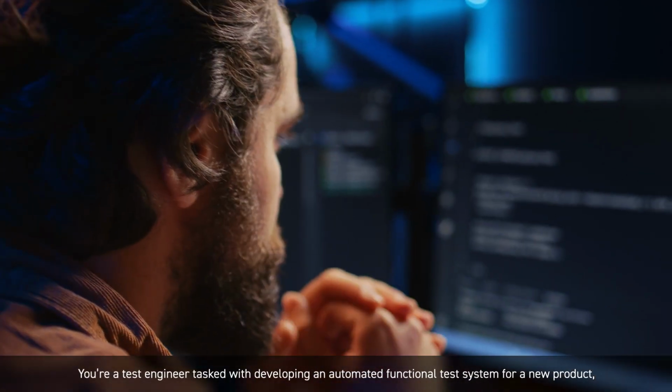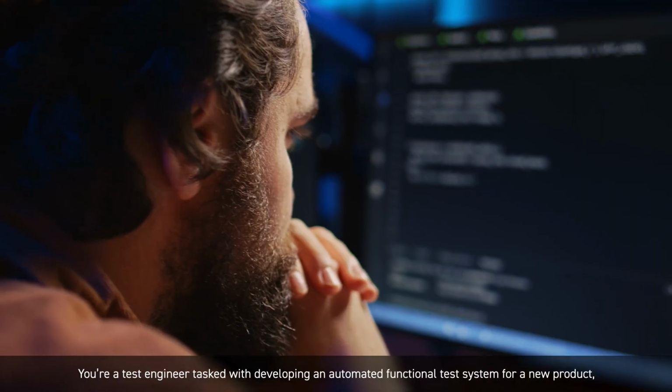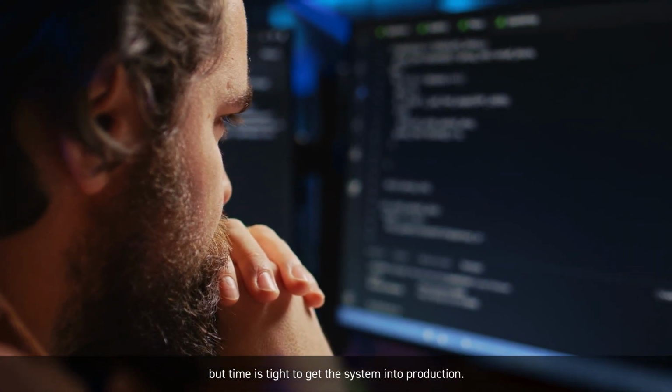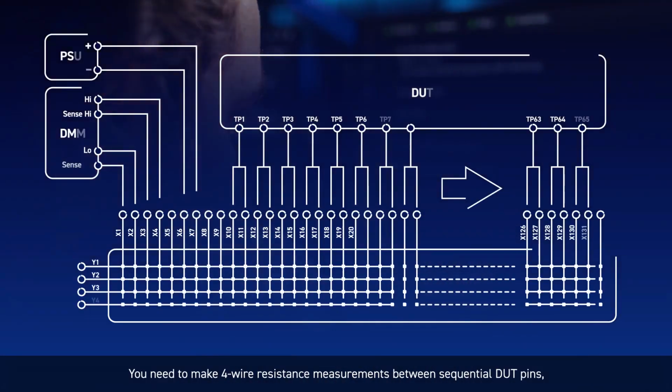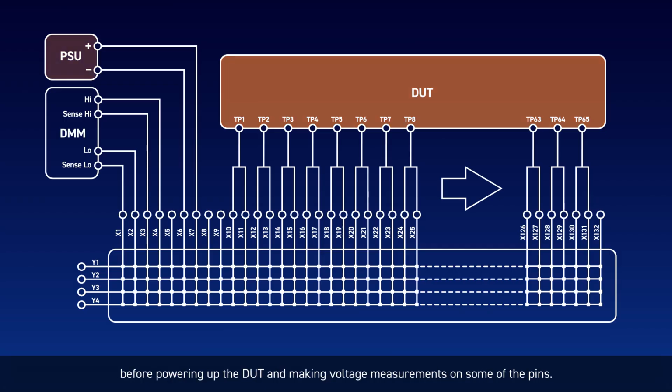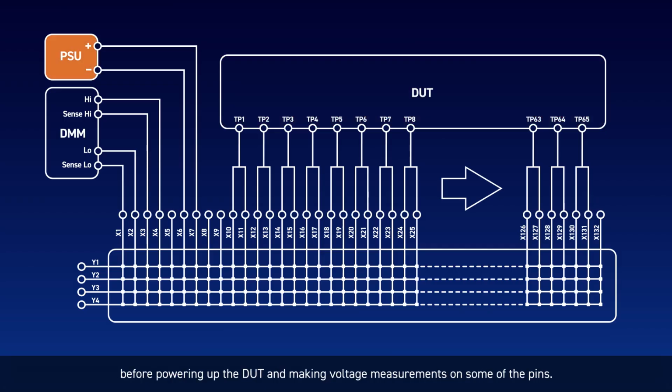You're a test engineer tasked with developing an automated functional test system for a new product, but time is tight to get the system into production. You need to make 4-wire resistance measurements between sequential DUT pins before powering up the DUT and making voltage measurements on some of the pins.